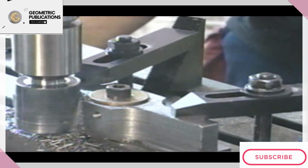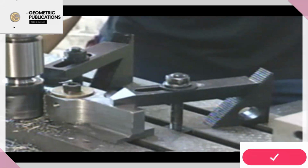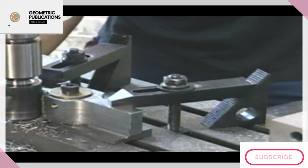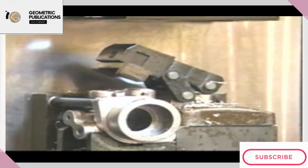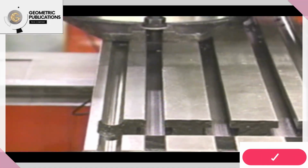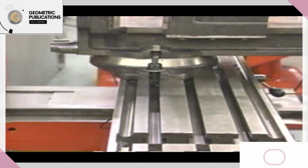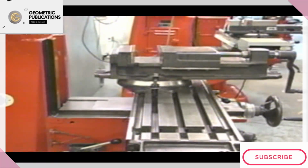Work holding devices in CNC milling include those standard vices and clamps already noted for work holding on knee mills, as well as devices specifically designed for machining centers. The T-slots of the machine table are still the primary means of holding work and work holding devices to the machining center table.